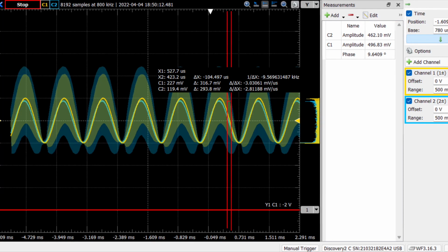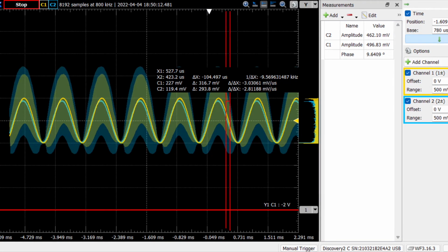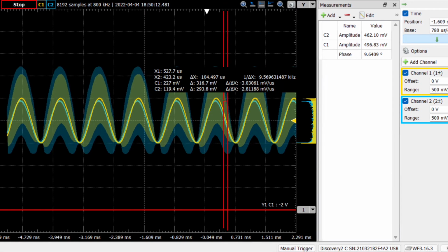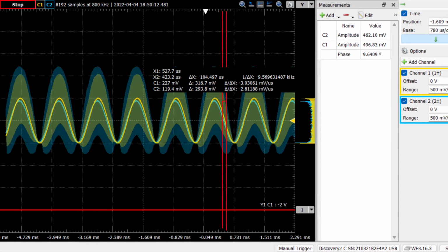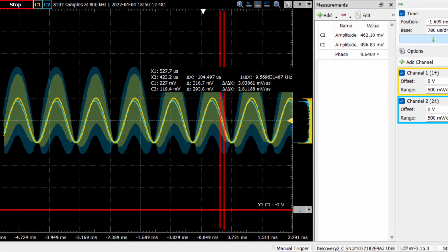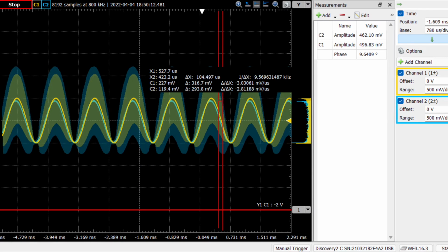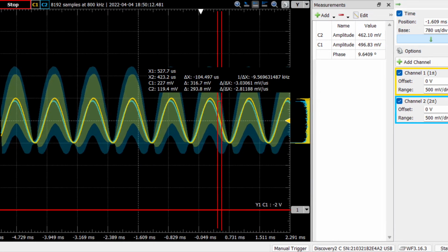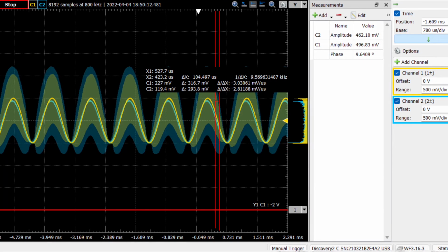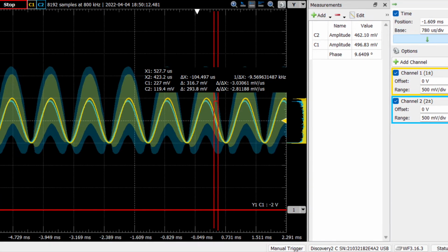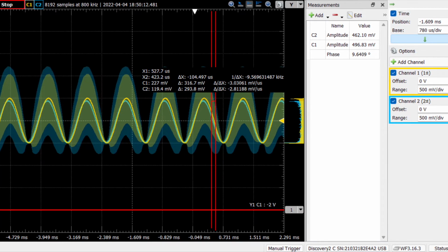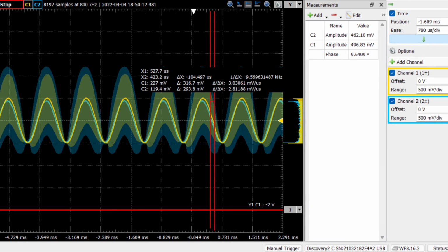Using waveforms, you can also look and compare the amplitudes of both of the channels. As you can see in the measurements column, both of the amplitudes are very close to 500 millivolts, which is the required amount for both the input and output voltages. You can also tell that the phase difference is very low, which means that they are within the 10% attenuation.